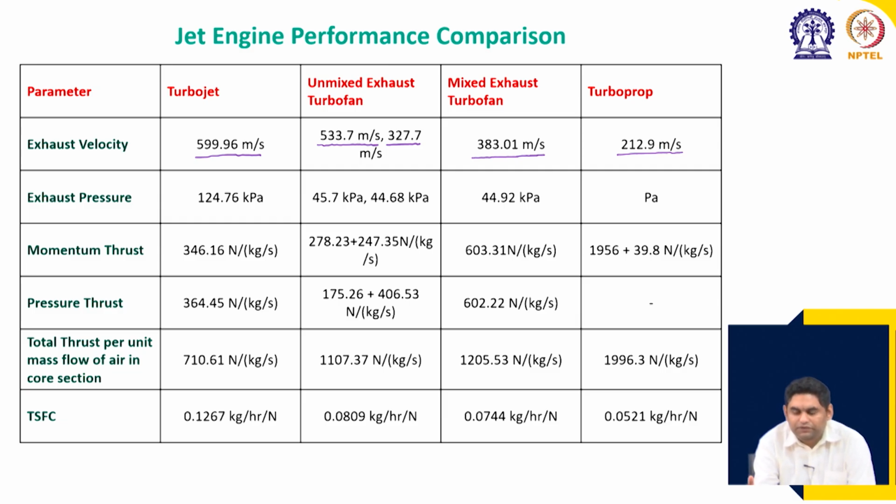Okay. Remember, the aircraft is also designed to fly at lower velocity, 0.6 Mach number, and we do not know what is the velocity after the propeller, because it is not possible to directly find that. But it is not going to be very high, because a very large amount of mass flow rate is happening and the thrust also is large, but this is due to the mass flow rate. Okay.